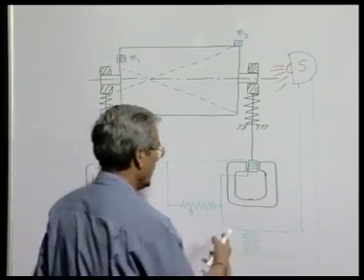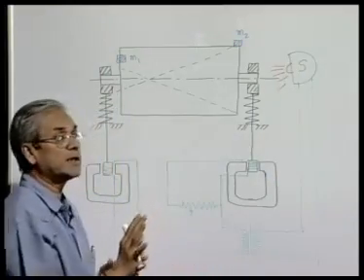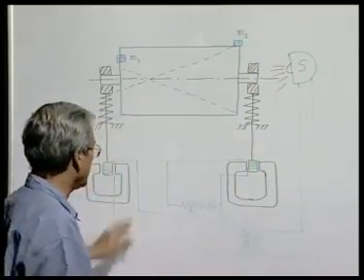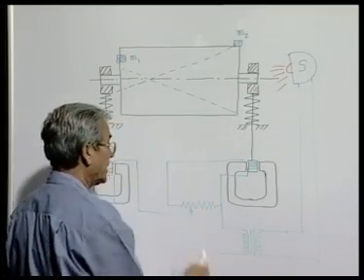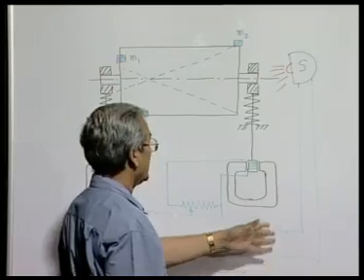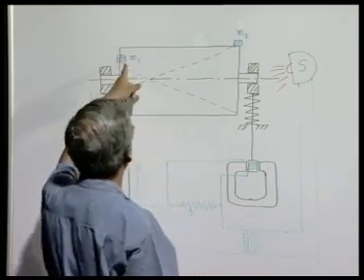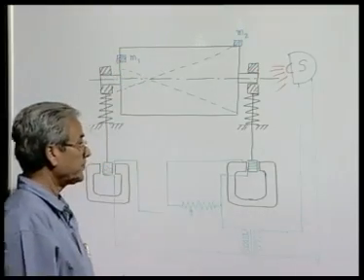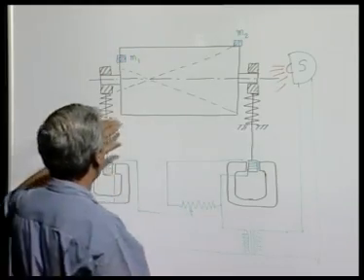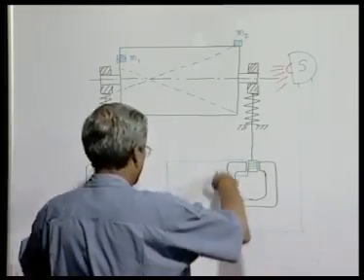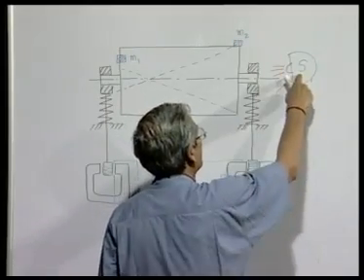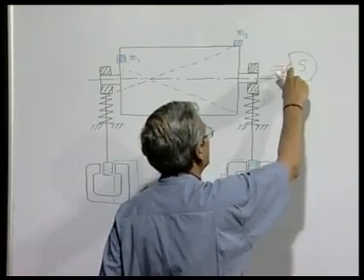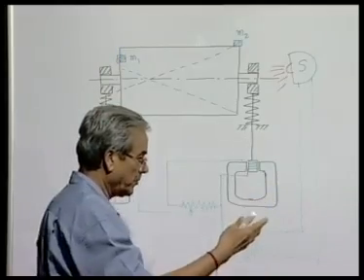So, effectively this circuit will now be insensitive to any unbalance produced at this end. Whatever voltage comes here, depending on the location of this potentiometer arrangement, is due to the unbalance which is really present, though temporarily we imagine it to be absent. Now, whenever this moves up and down and this voltage changes its direction, this stroboscope will flash for 1 microsecond as soon as the sign of the voltage changes.